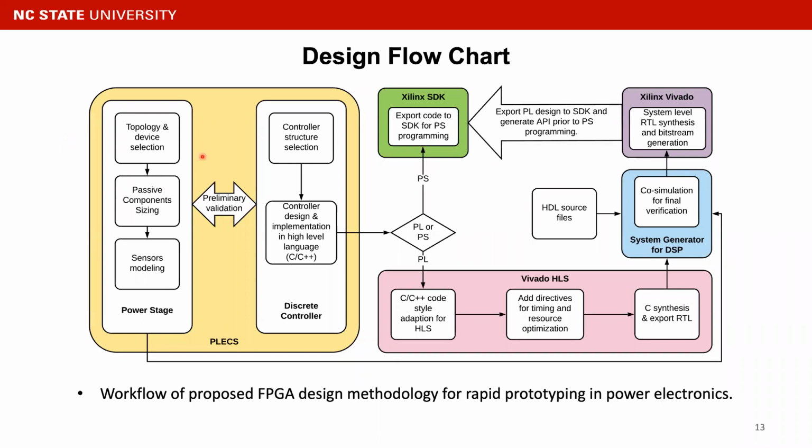And in Plexim, usually we can first select our topology and the device, size the passive components, and also finalize the sensor selection. In the meantime, on the software side, we will finalize our controller structure, and also we can implement our control design in a discrete manner, like in a high-level language. So in this, we can run a preliminary round of validation in a pure software environment.